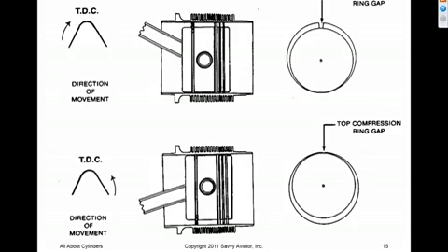But what this is emphasizing is that the compression test has an awful lot of noise on the data, and it's not a very reliable measurement of cylinder condition. There are all kinds of things that can cause low compression other than actual problems with the cylinder. We're testing the cylinder under very, very unrealistic conditions when we're doing the compression test. And there have been hundreds of thousands of cylinders that have been pulled off of engines because of low compression readings that were just fine and didn't need to be pulled off.